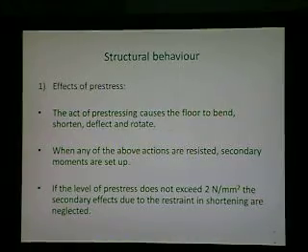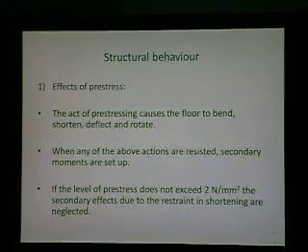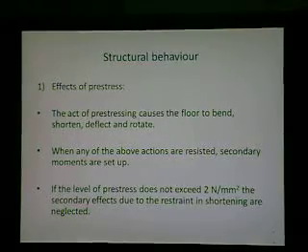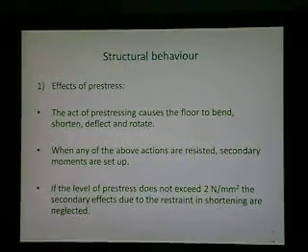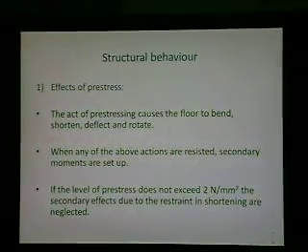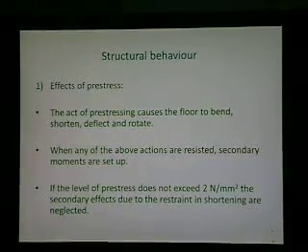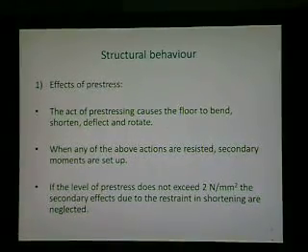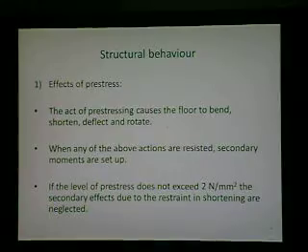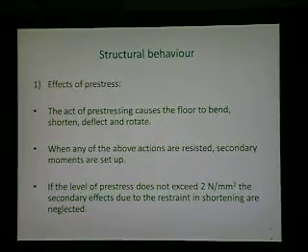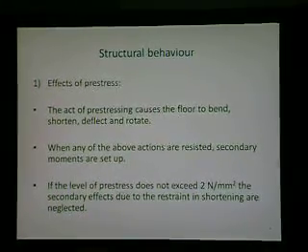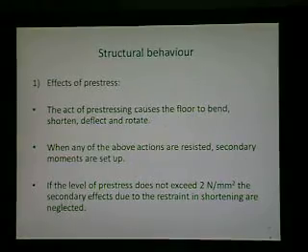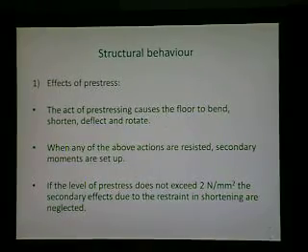Structural behavior. Effects of pre-stress. The act of pre-stressing causes the floor to bend, shorten, deflect and rotate. When any of the above actions are resisted, secondary moments are set up. If the level of pre-stress does not exceed 2 Newton per mm square, the secondary effects due to the restraint in the shortening are neglected.